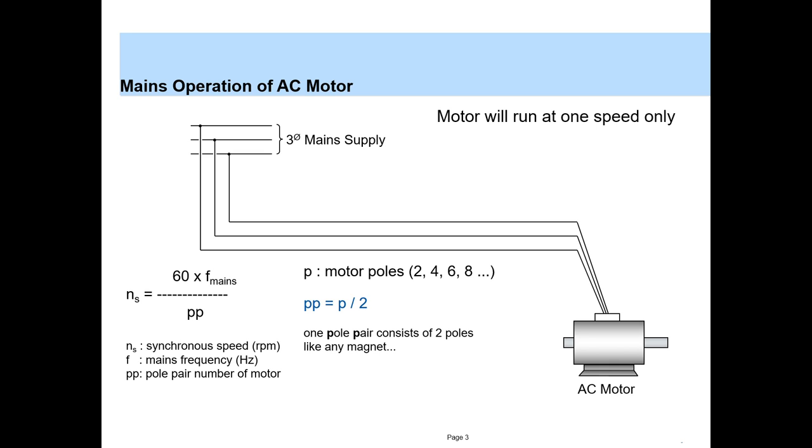In this situation your motor will always run at 1500 rpm, your rated motor speed. Let's say your pump application demands only 800 rpm. In this case you are wasting the rest of the rpm. You will be operating the motor at 1500 rpm, but your requirement can be met at only 800 rpm.